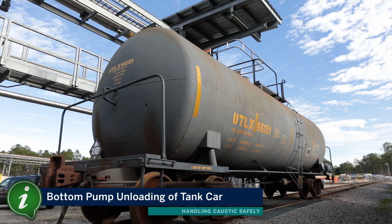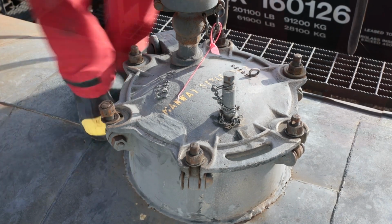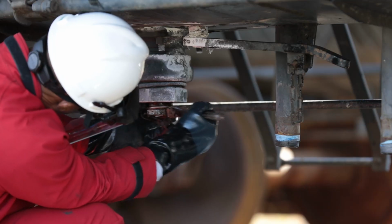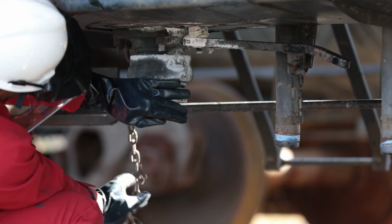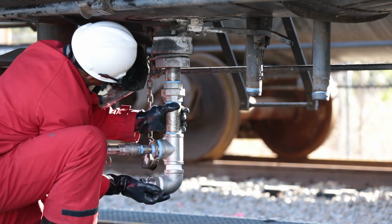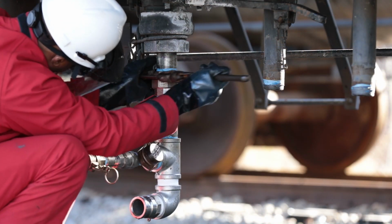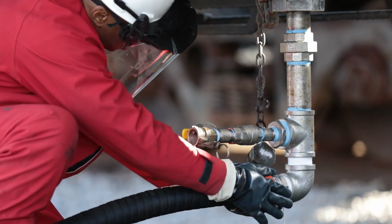For bottom pump unloading of a tank car, the following actions are performed. The manway is propped open for venting purposes and to prevent the potential of collapsing a tank car. Ensure the bottom outlet valve is closed and carefully remove the plug from the outlet fitting underneath the car. Install the unloading hose assembly to the outlet valve beneath the car and close the steam valve.